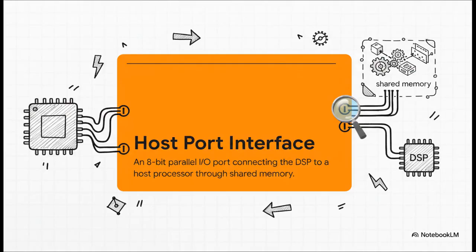And speaking of teamwork and multiprocessor environments, some versions of this chip feature an HPI, or Host Port Interface. This is an 8-bit parallel port that lets a master host processor directly read and write to the DSP's shared memory. It essentially allows our high-performance DSP factory to act as a brilliant, incredibly fast coworker to a much larger host computer system.